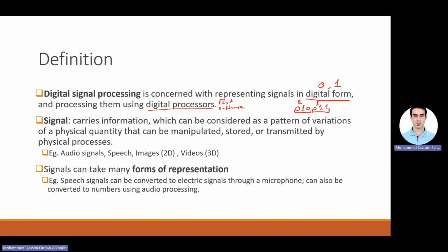So for example, if I'm dealing with filtering, let's say I have this low pass filter. Probably if I want to do some modifications, if I'm in the analog domain, I need to play around with R, C, L values to work out a suitable design for this filter. So there will be some hardware. But with digital filters, so that's the analog. And with digital, the hardware remains the same. It's like dealing with the chip, but I'll be changing the code, the software.